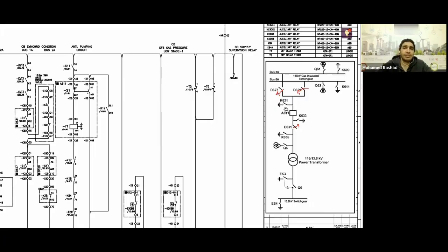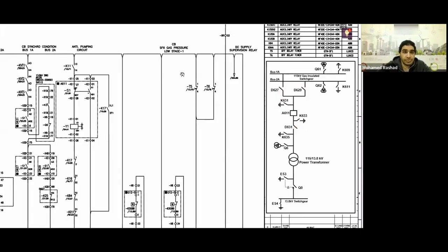So is it a condition, engineer, that in the Kingdom of Saudi Arabia, in order to close the breaker in the test position, I must necessarily have a ground before and after? No. The only thing that must be verified or must happen is that the blades before and after must be open. The matter of grounding is up to you as an operator to close it as a safety measure for yourself, okay? Or as a person in charge of what? Is that clear, engineers? Very good.